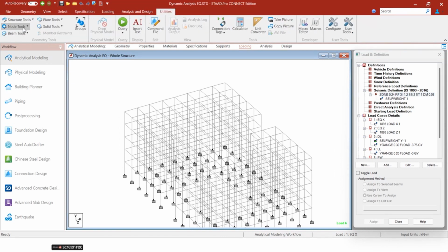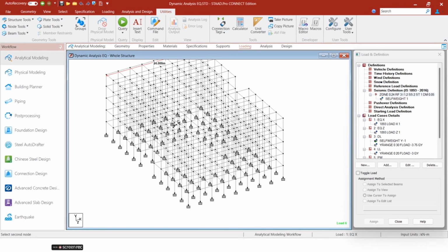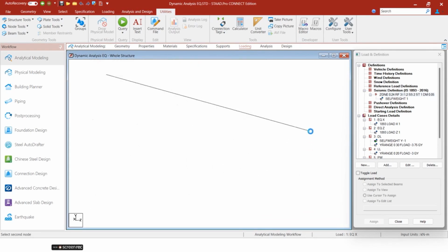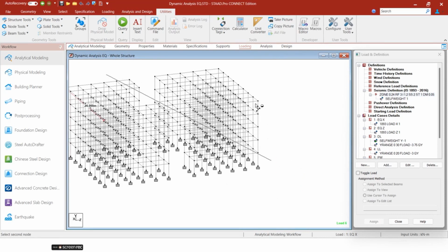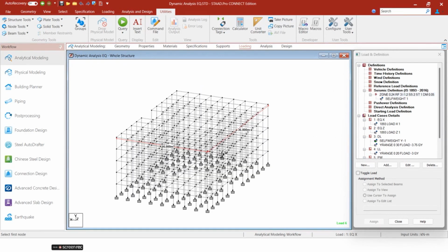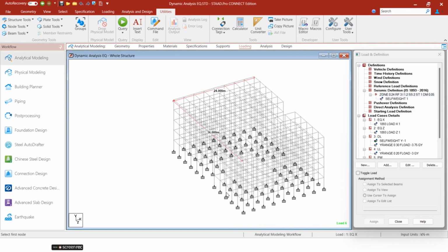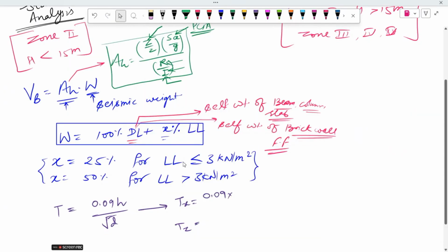So you can go to the utilities, go to the beam tools and node to node distance. So from here to here, this is along what? This is along my X. Okay, so along X that is 24 and along Z that is 36. Okay, 24 and 36. Click on escape and go for entering the values.